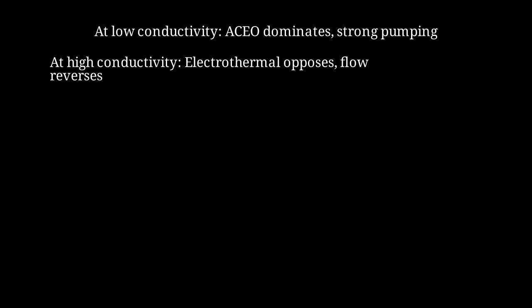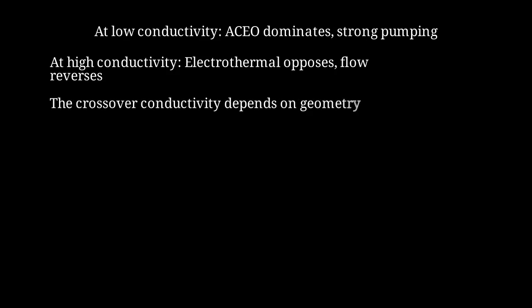Worse, it often pumps in the opposite direction. The net flow reverses. Your pump becomes a pump that pushes the wrong way. The crossover conductivity where flow reverses depends sensitively on geometry. Electrode width, gap size, channel height all matter. Predicting the crossover point requires detailed simulation.